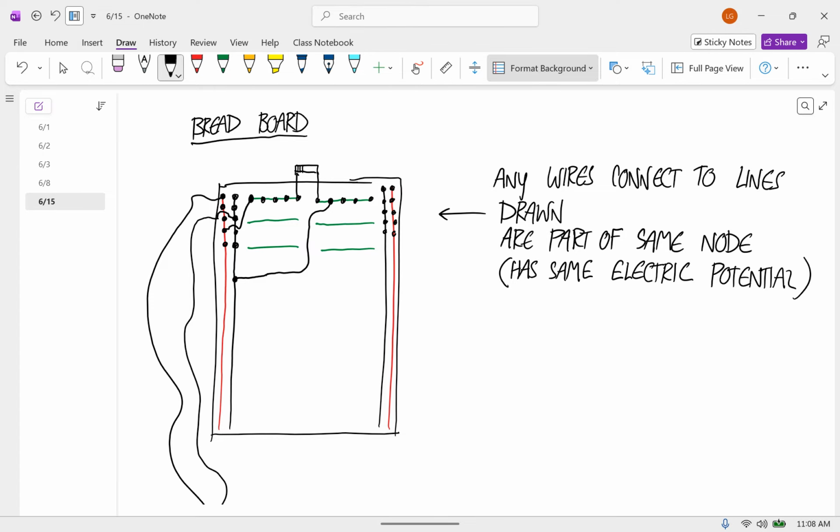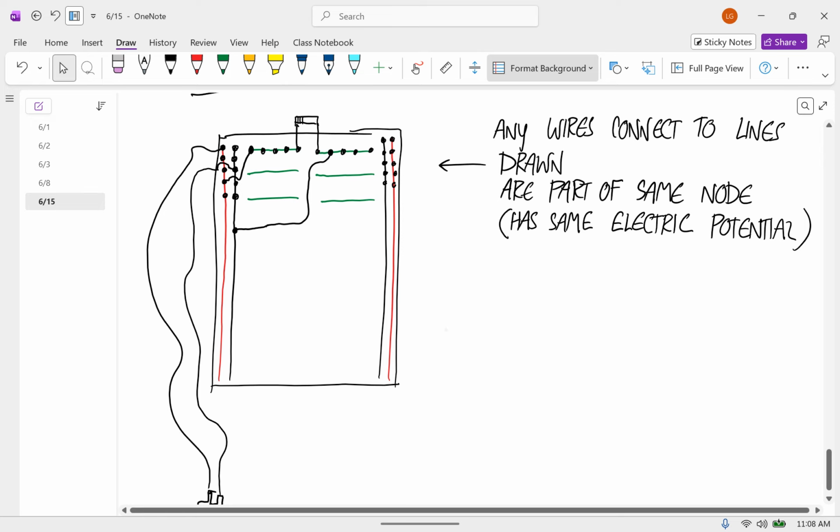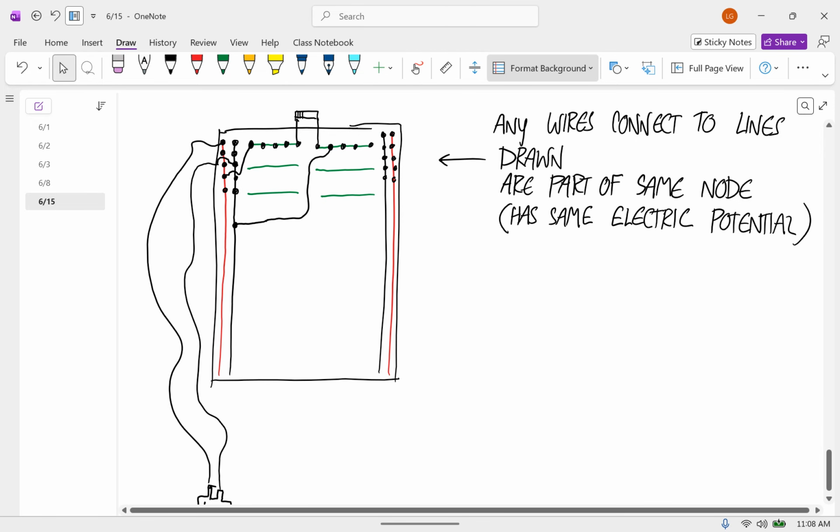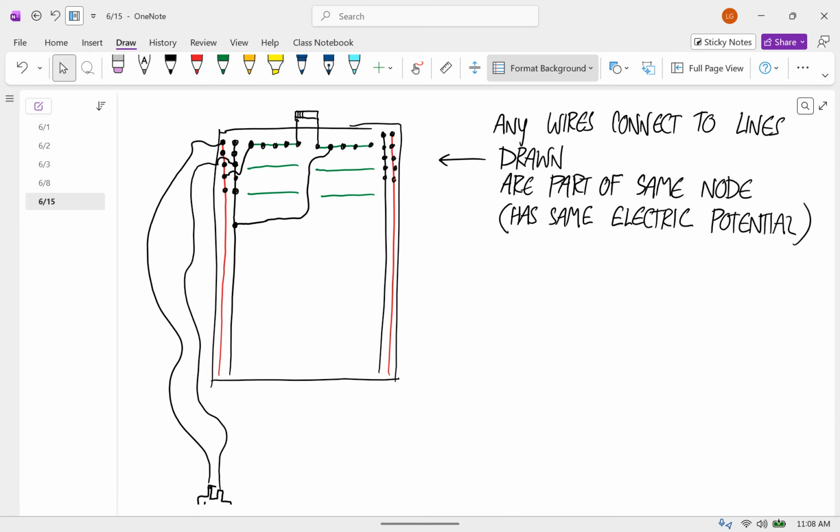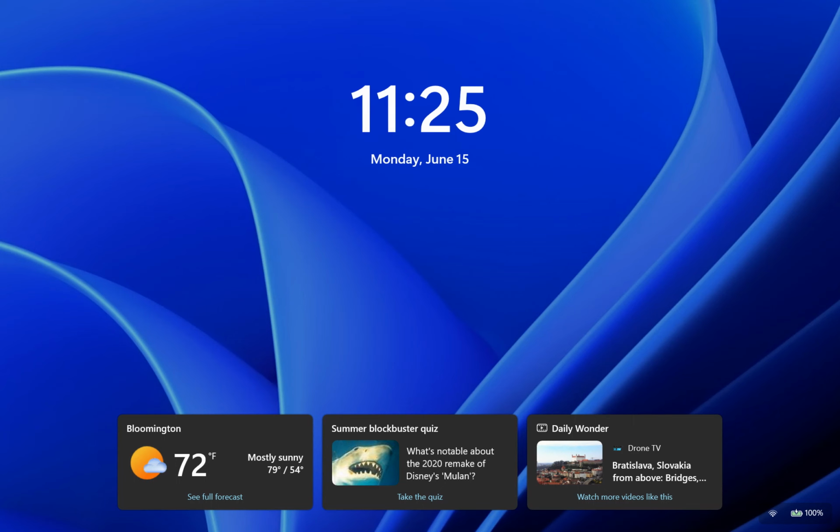And that breadboard will just hold all those connections in place. Now it looks a little messy, but it's not physically messy, like trying to connect alligator clips. We're going from positive to this rail, which connects to here. So we're going positive to here. Then it's going through the resistor, because this doesn't connect to this except through the resistor. And then from the negative of the resistor to here. Okay, well, let's get out the breadboards.